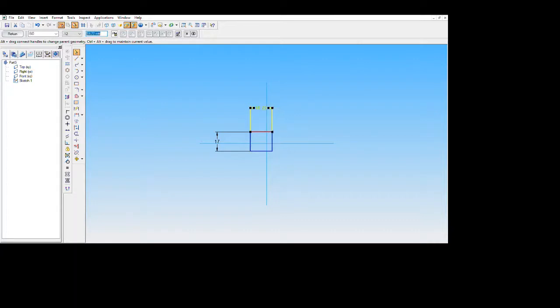18.72. Now many people would have a doubt. We can directly form the hexagon by running the run macros command, but here they are given two dimensions, that is 17 and 18.72, but in the run macros command it takes only one dimension, so we have to form the hexagon manually. Now as the rectangle is formed of given dimensions, now go with the connect command, select the midpoint and select this plane, select this midpoint and select this axis.